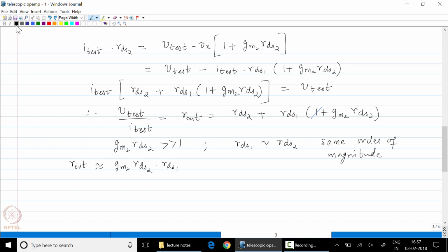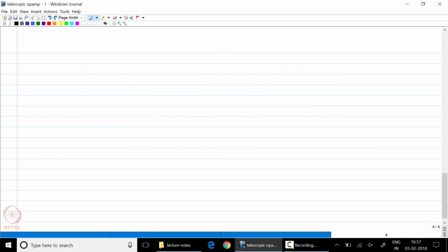So now let us go back and try to implement this in our op-amp. If I were to build an op-amp, now I know that my input should now have a cascode portion, because the impedance looking down needs to be as large as possible. So now I am going to connect both these voltages to the same voltage. I'll call that VB2.